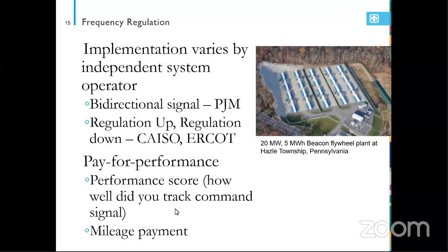So if you wanted to, you could charge your battery system all the way to full state of charge, and then just provide regulation in one direction and keep discharging until you reach a level where you want to charge back up again. So having the split markets does offer some additional operational modes.